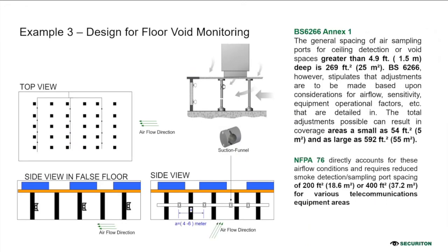We look into the fab areas, sub fab areas, and we also now go down. The third example will be the floor void. As we are aware, the air circulation inside the clean rooms will be drastic, or the airspeed is in high movement motion, so it needs a certain adjustment in terms of the standard distances in the sampling hole.